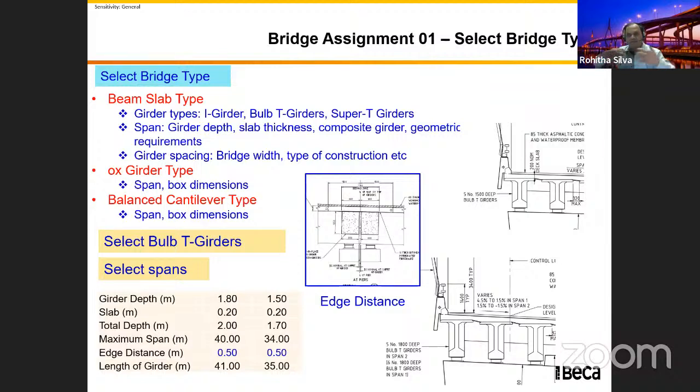And if you know your bridge span, then you can calculate your bridge span arrangement. If you know the number of spans, that means you know the center line of each and every substructure. You know how many substructures we need to build. Of course, we need abutment A and B. In between, how many are needed. That's how you're going to calculate it.